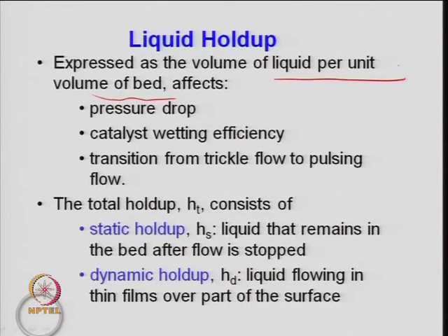One can look at the flow visualization or concentration and pressure drop at different locations, radial, axial, and at different positions. So, the volume of liquid per unit volume of the bed is known as the liquid hold up. This will affect the pressure drop: higher liquid hold up, more pressure drop.